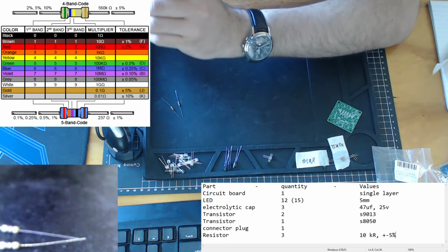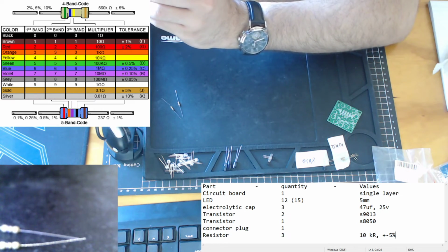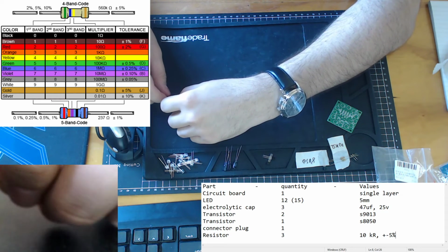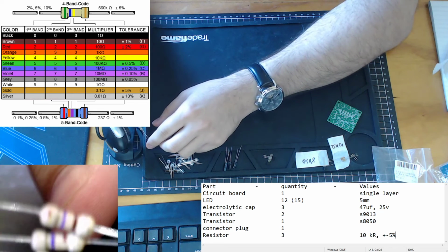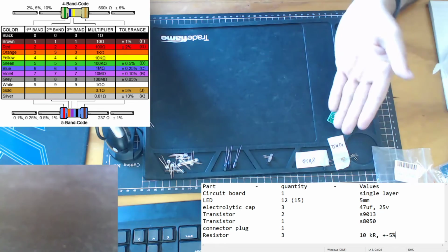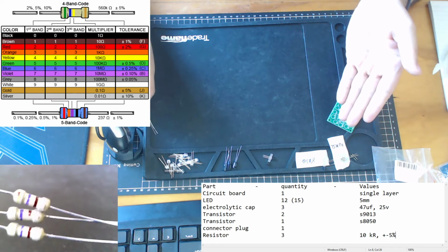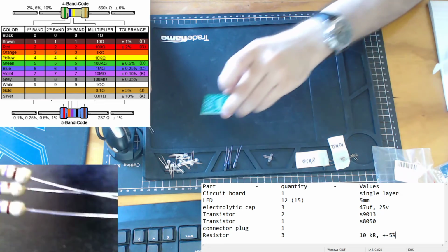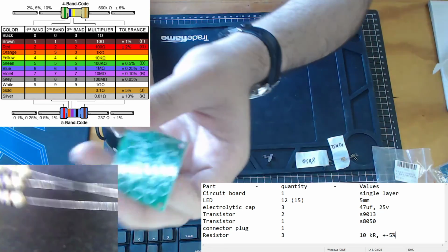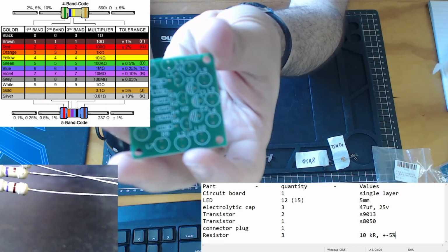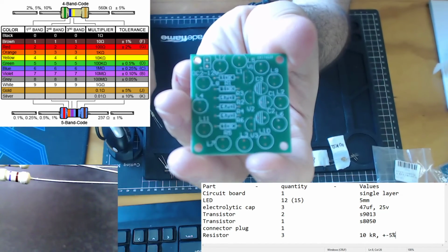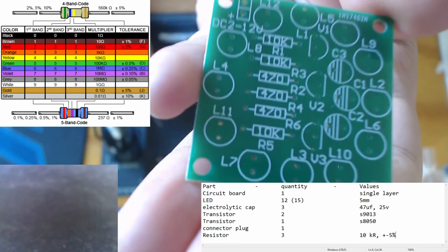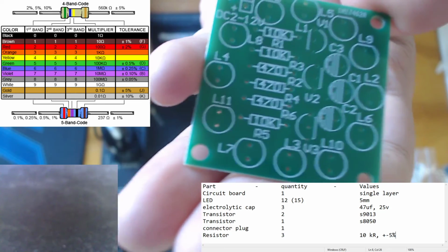So what this means is we need to use some sort of investigation to find out what the values of these resistors are. We can either find a circuit diagram for our circuit and then work out, based on the resistors we know, we have 10K resistors, but we don't know exactly what these ones are. We know that our circuit diagram requires 10K and 470K resistors, so we can already guess that this is going to be 470.